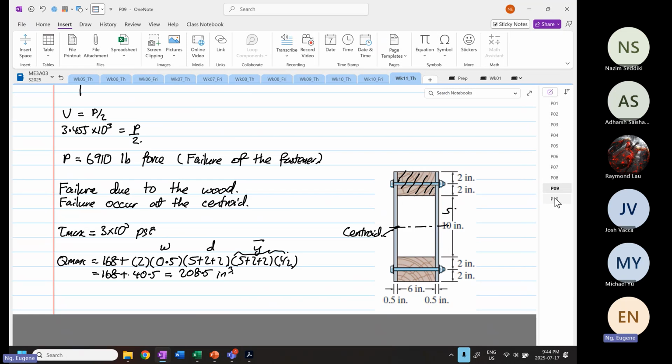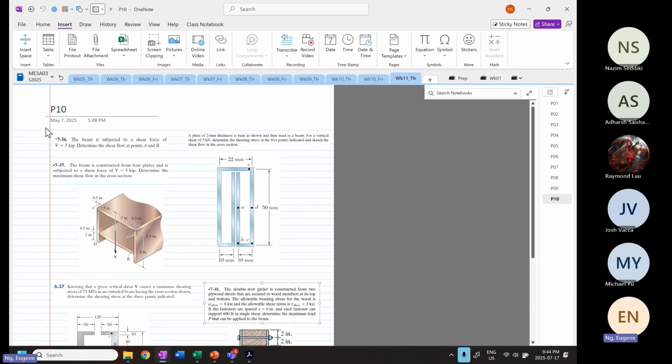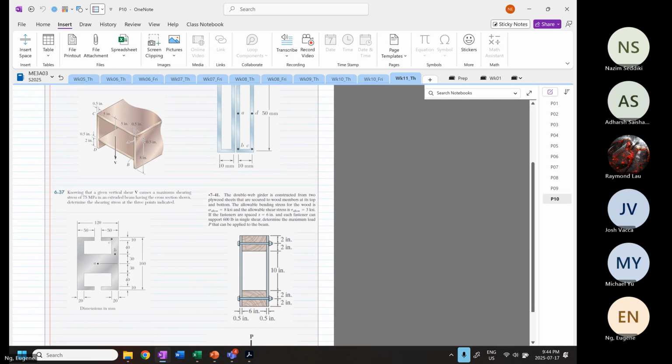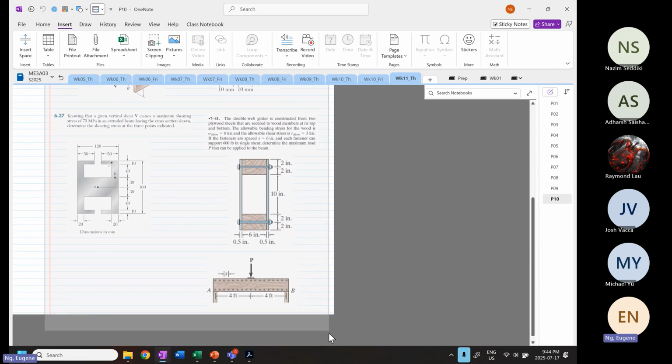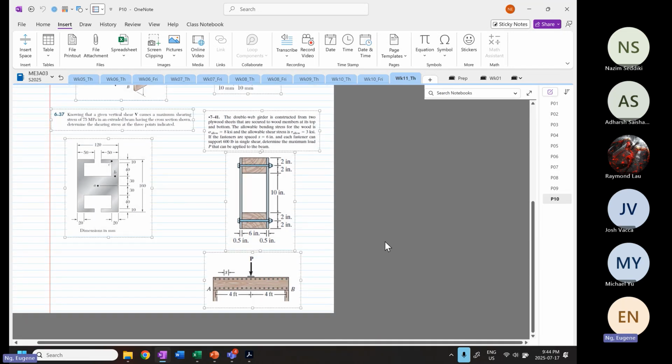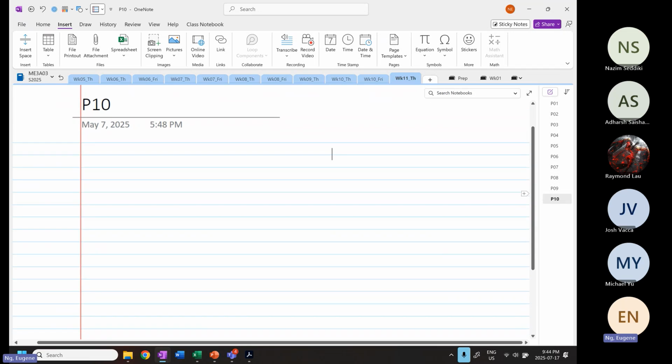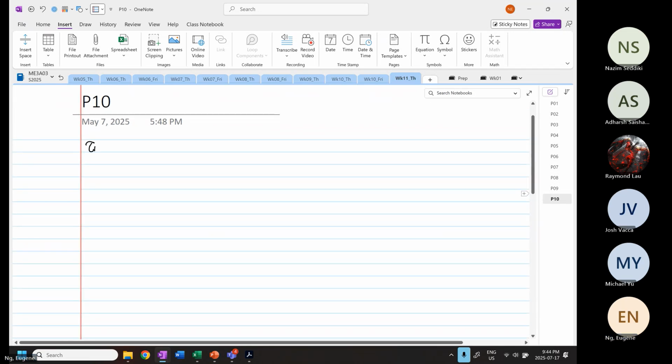Okay, now we just need to plug in the formula. Let me delete all this. Again, you can see all the analysis we do down here, first moment of area is the most critical thing, right? So you have tau max is equal to VQ over It, right?